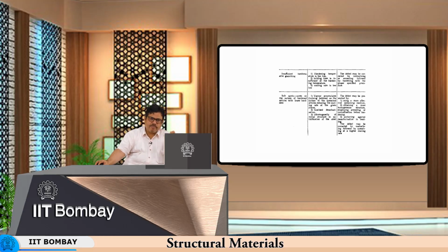Now, if you are quenching in a salt bath type of furnace, then this bubble formation can be avoided completely. So, it is a very effective quenching medium. In fact, a salt bath therefore gives you a very good quality of quenched product. And you have a more homogeneous structure by annealing, and annealing and normalization are things again which lead to homogenization.